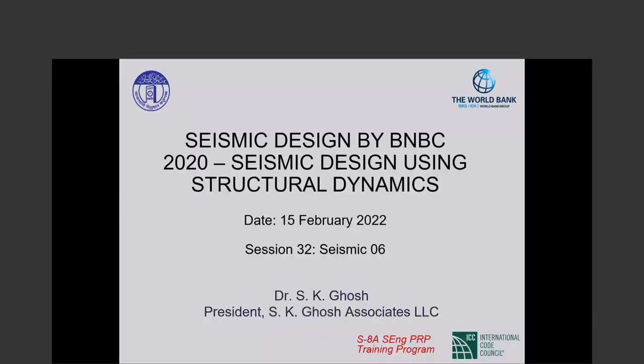He just mentioned a seismic design using structural dynamics. We had a significant number of specific requests for this topic, so I decided to include it, and we will see how it goes. When it says structural dynamics, we will specifically use the so-called modal response spectrum analysis in the design of structures.